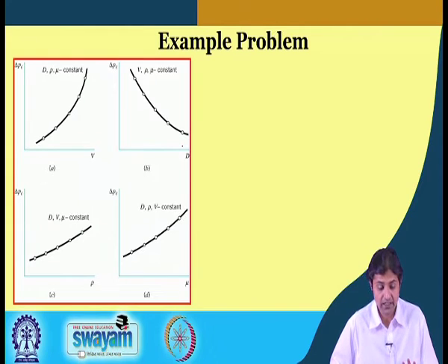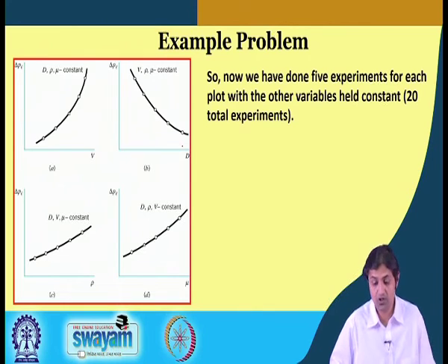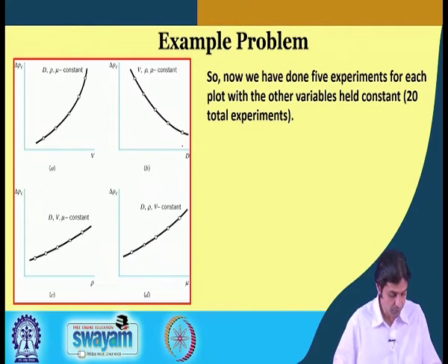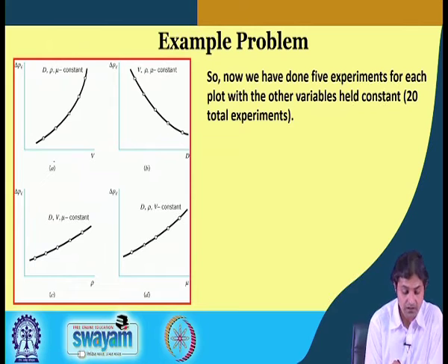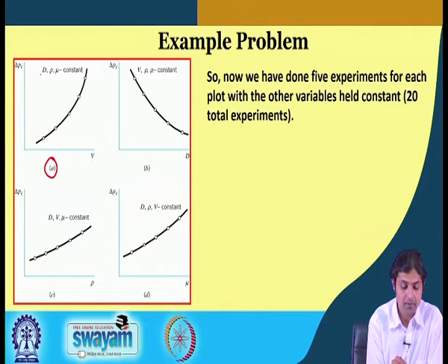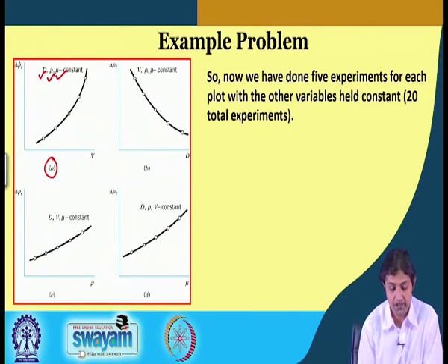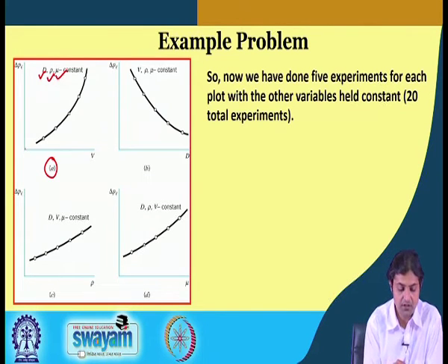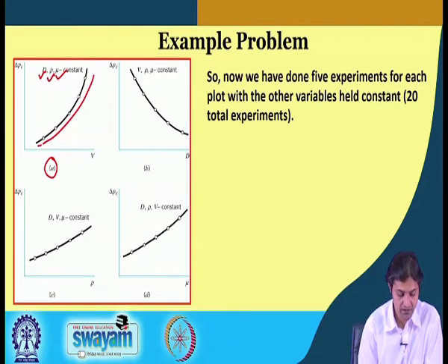So, the right hand side is the plot. I am going to explain to you what those plots are. If you look here, graph A shows that we have varied the flow velocity, we have kept diameter, rho and mu constant, and started measuring the pressure drop per unit length using our apparatus. What we find out is the pressure drop per unit length is increasing as the velocity is increased. This is a sort of a curve that we are getting.